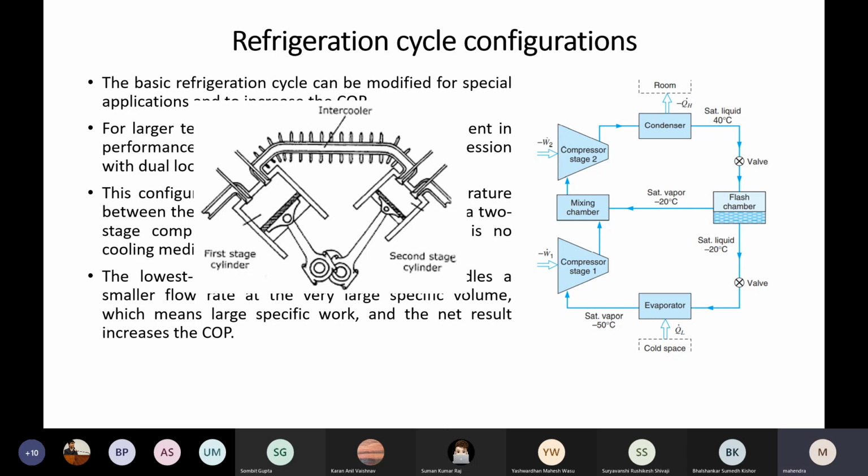Along with the pressure, your temperature also increases. Such a hot fluid, further you are handling and then passing to the storage unit, the air itself would be very hot, and handling the piping system also would be a problem. And along with that, if this compressor works for such a long time, then compressor wear and tear also would be very high.